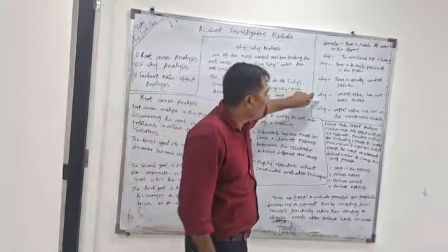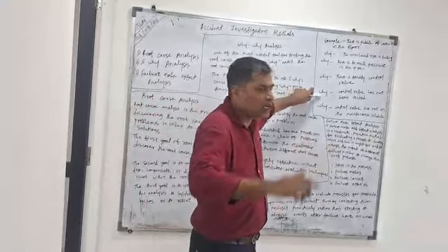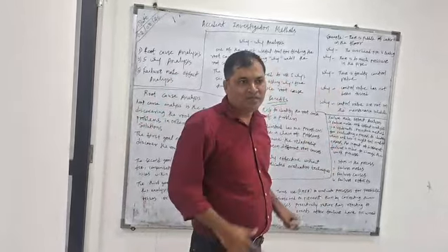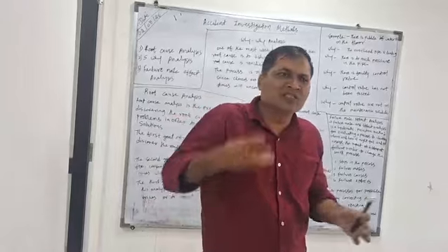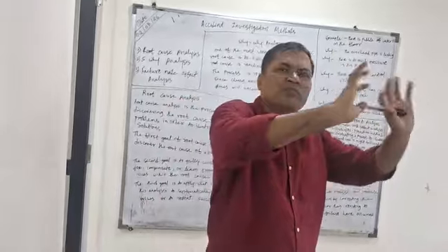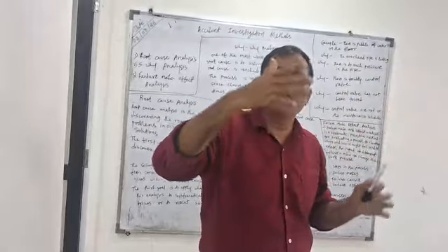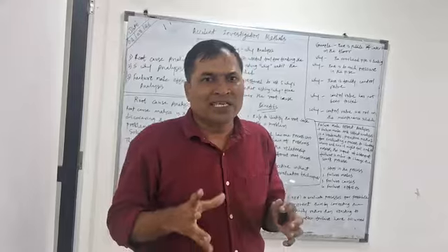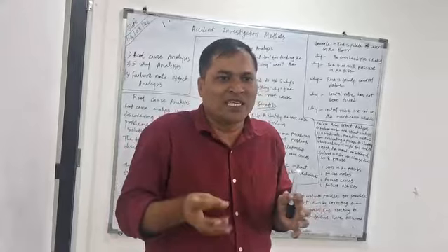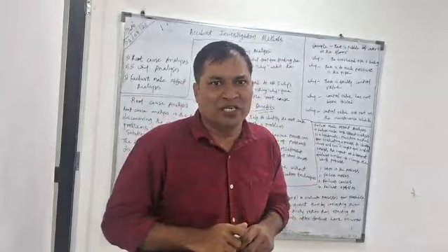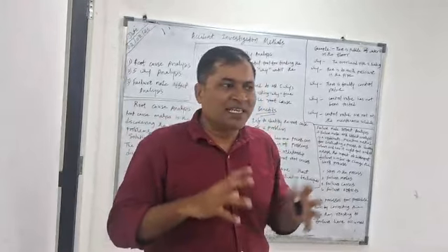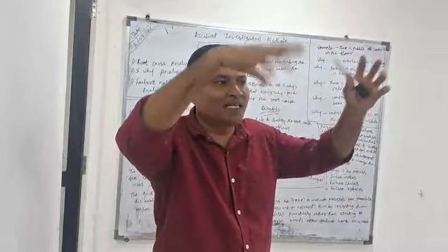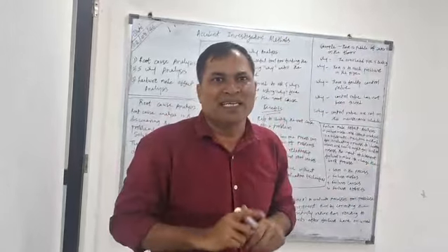The next why: again you have to ask some other workers. The control valve has not been tested. There is no testing system. You just put the control valve in once, and after that, no checking, no testing, no third-party inspections, third-party checklist, or third-party investigation. It is very important related to the control valve. If your control valve fails, the main pipe starts dripping, and there is no maintenance.